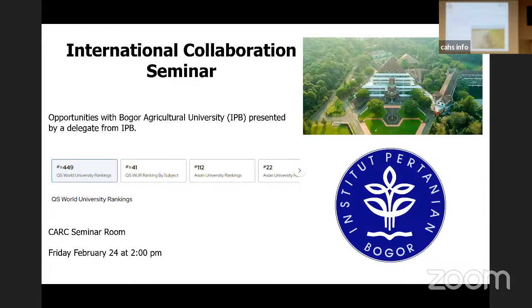One of the things that I have been investigating for the last 2 years, but that's not in slope, that's for the landfill application, is the engineered turf. Turf is a composite geosynthetic material with synthetic turf and geocomposite. I tried to see if we put any synthetic or engineered turf materials over the soil, and I also have a control section where there is no engineered turf, and I compared the results. The turf is actually retaining moisture equilibrium. Moisture equilibrium means there is no significant gain or loss of moisture because of the environmental fluctuations.